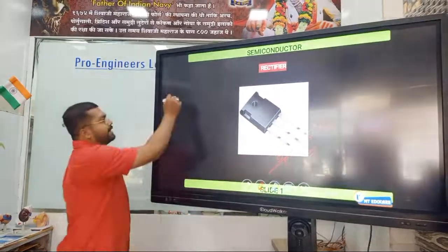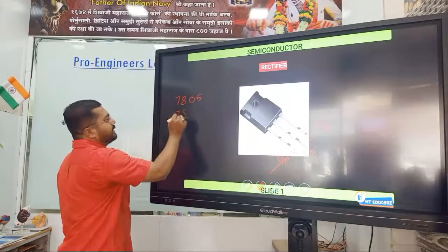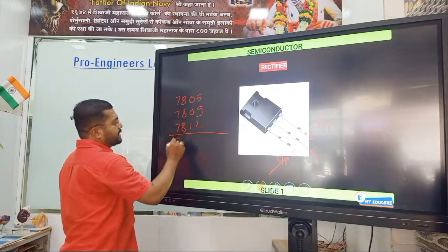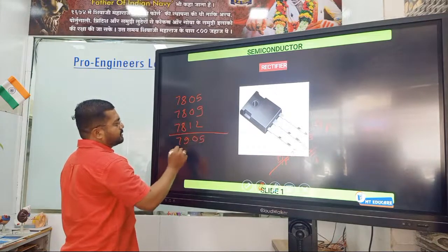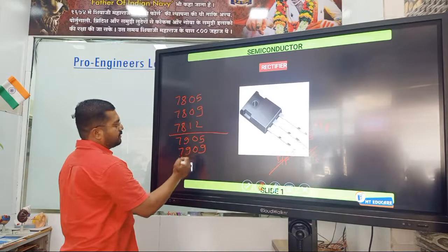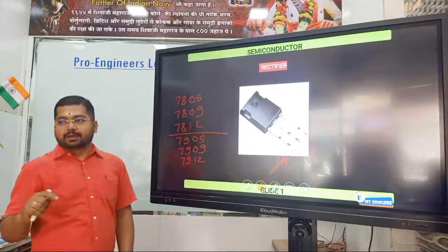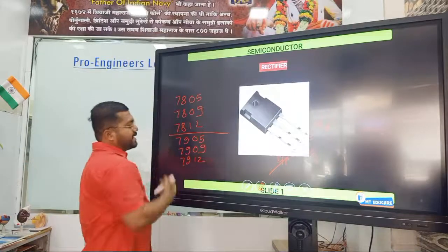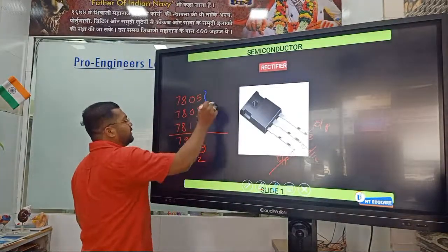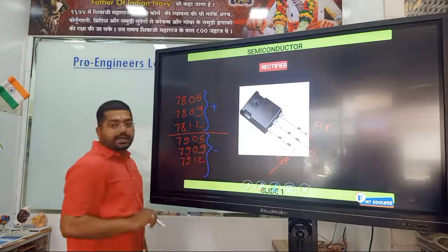Again, in the market there are some series available: 7805, 7809, 7812, 7905, 7909, 7912. These are a few series available. Now what does this stand for? The 78 series stands for positive output, and the 79 series is for negative output.